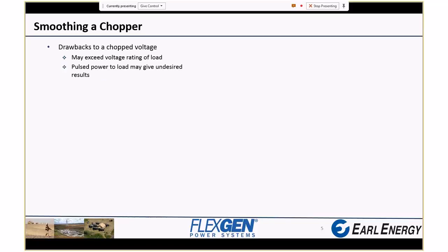So the motor turns at twice the speed it might have at 5 volts for half the time, and then it stops when the voltage is 0. Well, from the motor's perspective, you still may get the average speed you wanted, but you're going to get it in these jerky motions, and that may not be the desired result. And there are other problems like that going on.